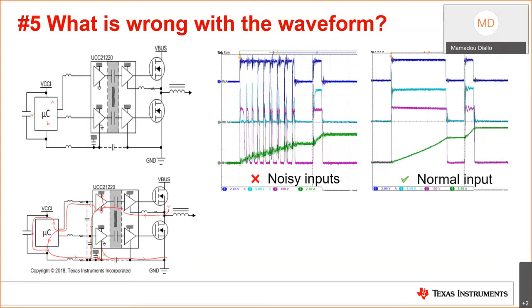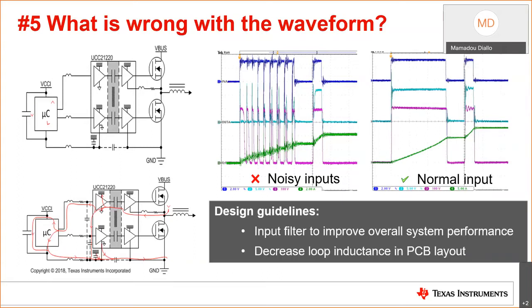It is typically recommended that users avoid shaping the input signal of the driver IC, but for this specific case, it is better to have a small RC filter to mitigate the ringing caused by the non-optimized layout and the very high di/dts. Such a filter may use resistor values as high as 100 ohm on the input and capacitor values as high as 100 pF.